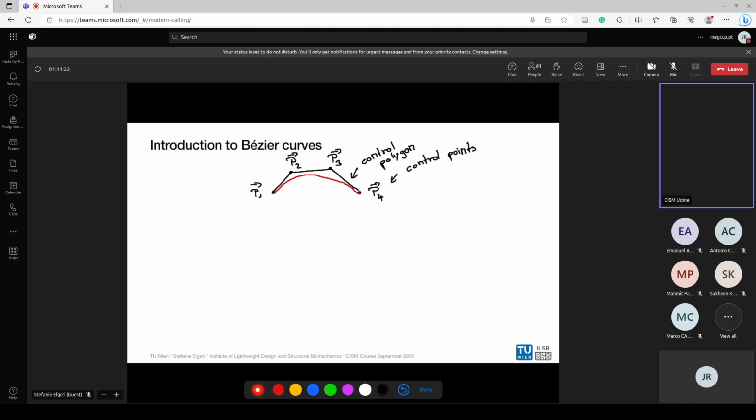How do we generate the curve? So the expression that we have to evaluate is that curve coordinates. So C vector are the curve coordinates as a function of the local parameter psi is equal to the sum over all control points, from I is equal 1 to n, of a basis function, B_I,P of psi times the control point coordinate.